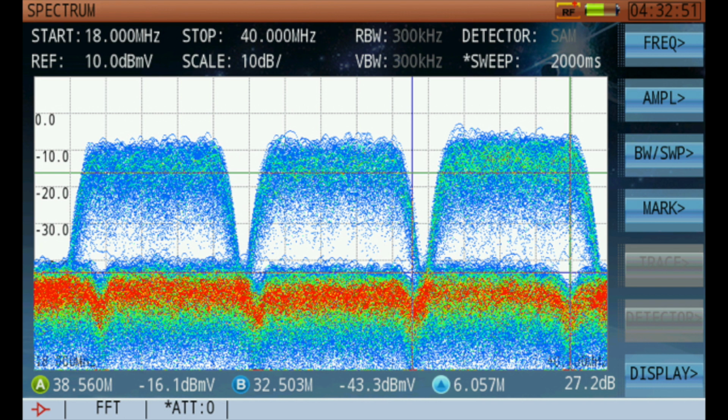When looking at the overall RF energy and displaying it all as a series of bitmap points rather than a swept trace, which typically only reveals parts of the RF signature. In other words, it's a graphical representation of RF energy, and the color of the bitmap will depend on the percentage of RF signal occupation. For each bitmap point is a set sweep time.